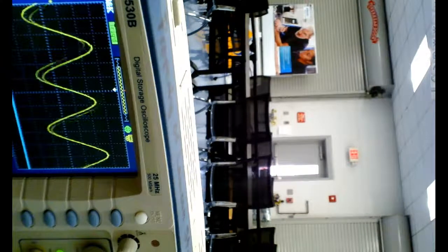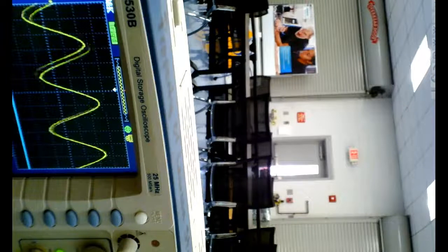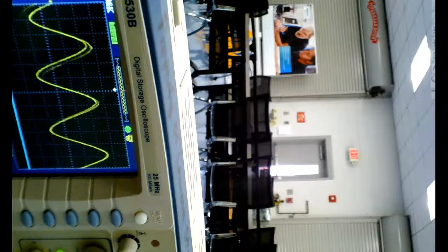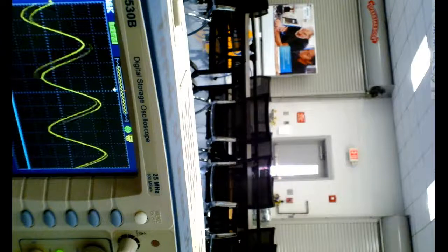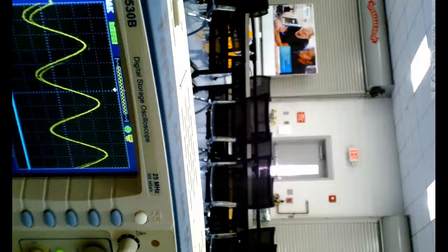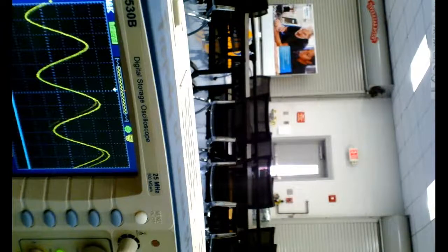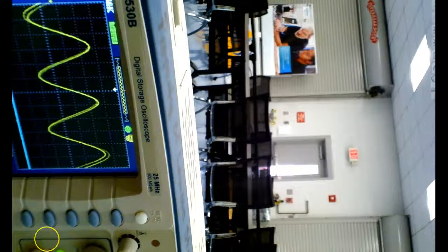But the problem is we've got to have AC on these things. So if it's a DC circuit, that means inside there we have to have an electronic circuit that we call an oscillator, right? You understand that generates an AC inside the sensor, and then we've got to have a circuit in there that senses the change. Are we okay? That makes sense. Pretty neat. Most of these things, though, are two-wire. How can they be two-wire if they're electronic? Well, they power up through the circuit itself.